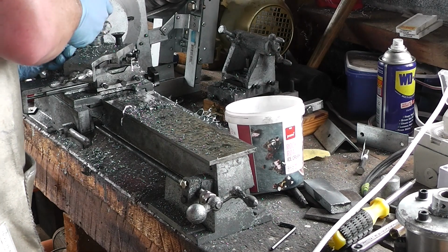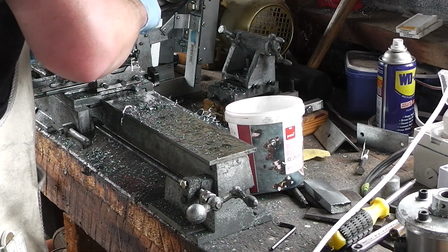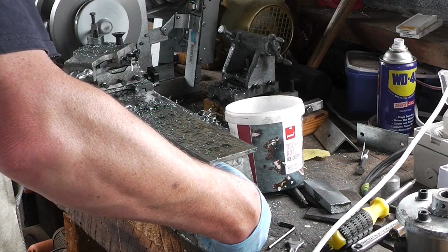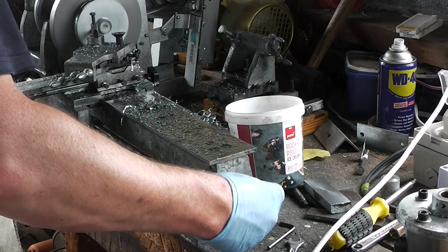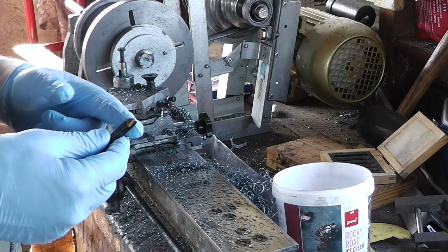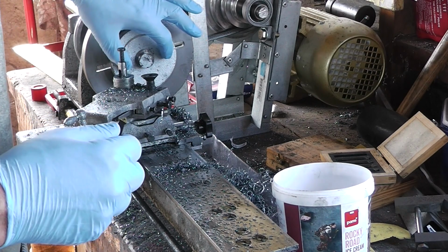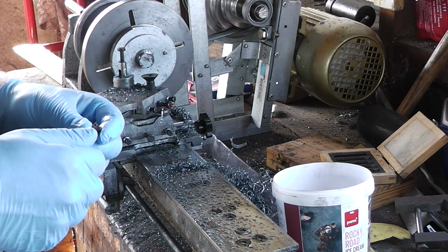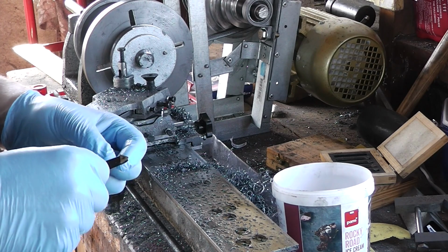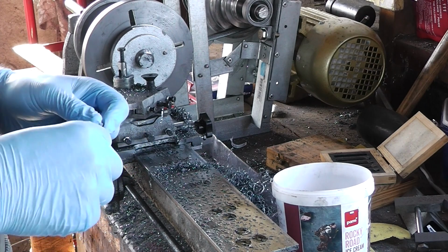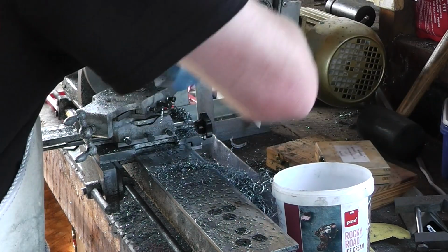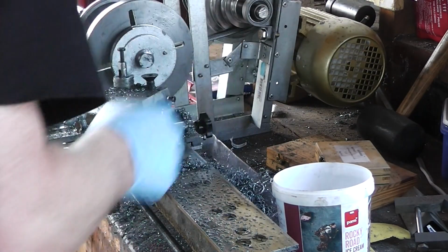Carriage is hitting the blasted thing. Well, I was trying to face off the surface, and it seems to have been forceful enough when it hits the steel screws that the thread on the insert, or the thread on the little bolt holding the insert in, seems to have stripped a bit, come very, very loose, which I'm very annoyed about.